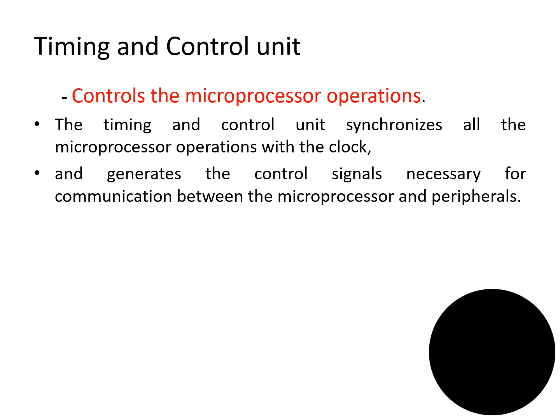Whenever you want to write into memory or take data from memory, we have the set of control signals RD bar and WR bar. When you want to take data from the memory, RD bar will be active. When you want to store data into the memory, WR bar will be active.